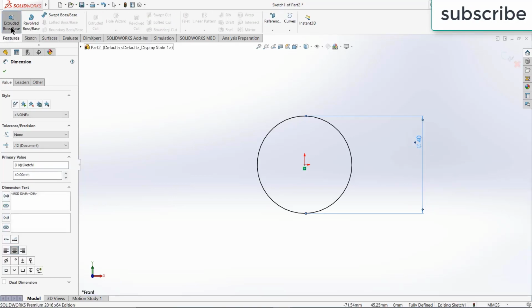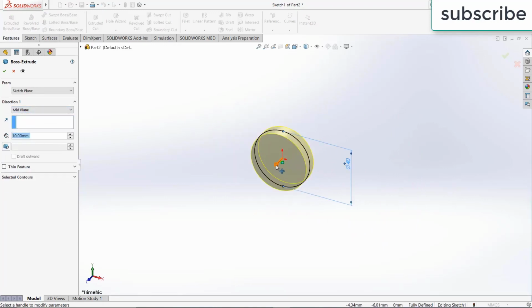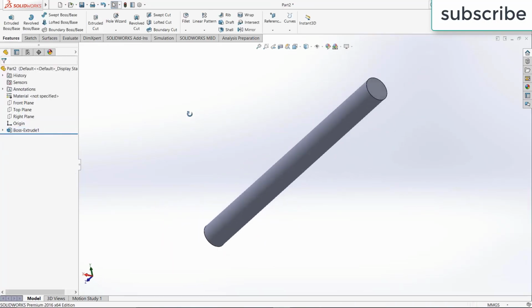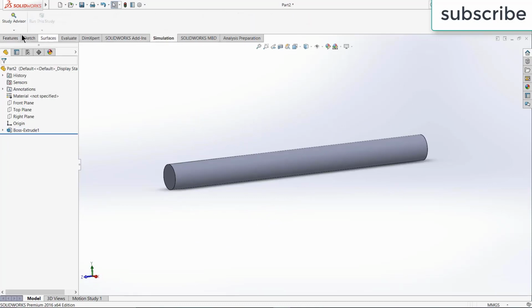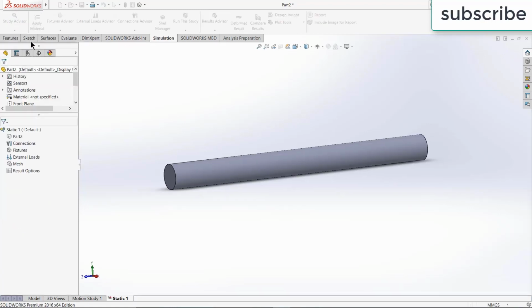Now go to features, click on extrude boss base, click on middle plane. Now increase it as per your length requirement. Click OK.